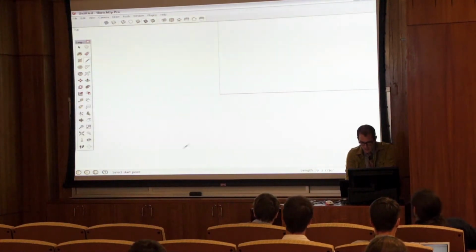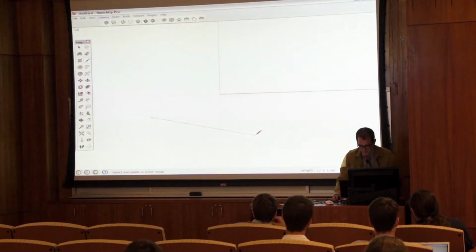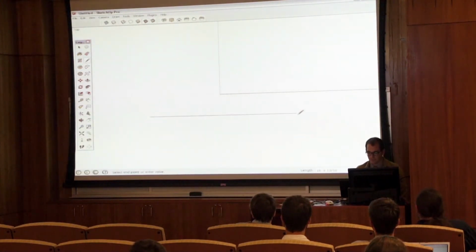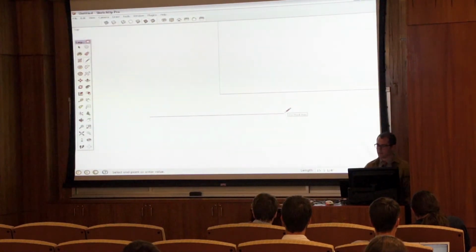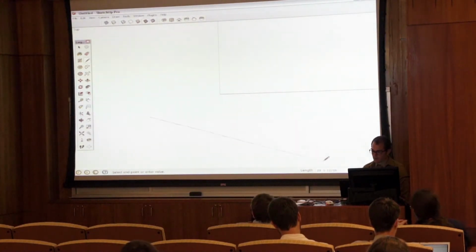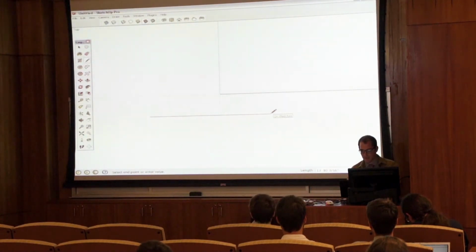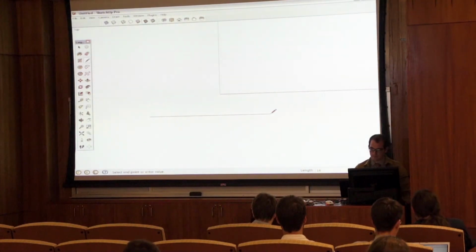So click on the line tool, start anywhere in this bottom left-hand corner. Go ahead and click and release just to start your line. And you'll notice you get this sort of rubber band effect as you're drawing with the line tool. You'll feel SketchUp snap to the red axis, which is your x-axis. You can also feel it snap to your y-axis, which is your green axis. And SketchUp's always waiting for your input. So as you draw that line, and as I have my cursor in that red axis, you don't type in the value control box down here. See this value box down here? You don't ever want to type in that. Instead, you just want to type on your keyboard wherever you are with your cursor. So in this case, if I want this line to be 14 feet, let's go ahead and type in 14 foot sign and press enter.